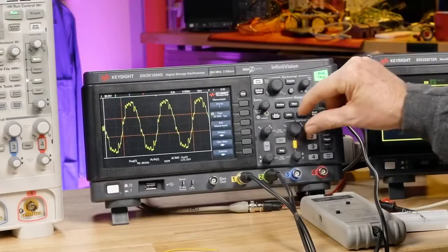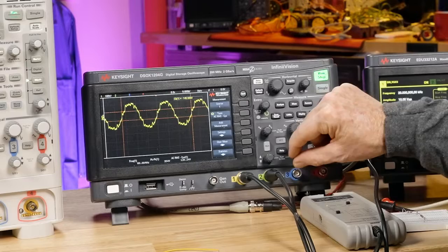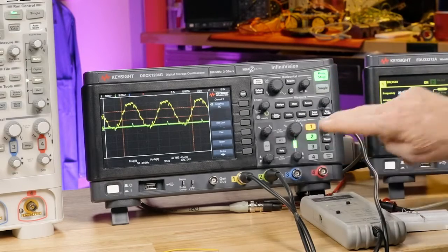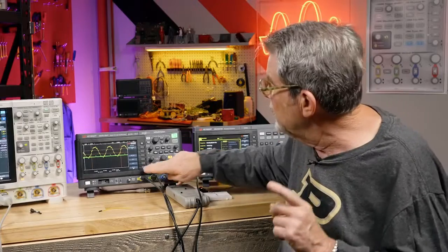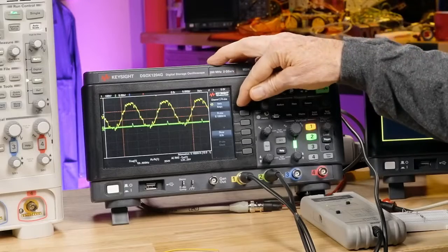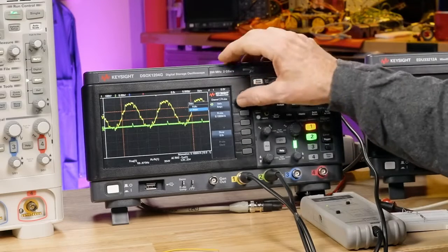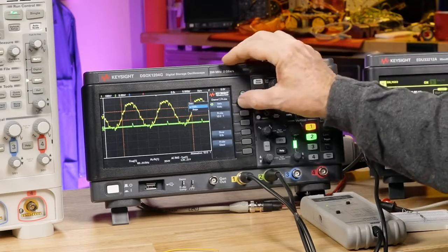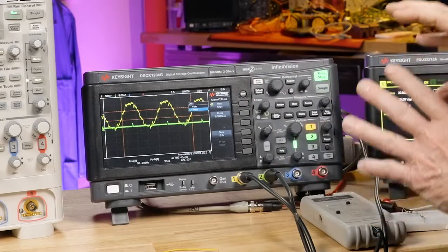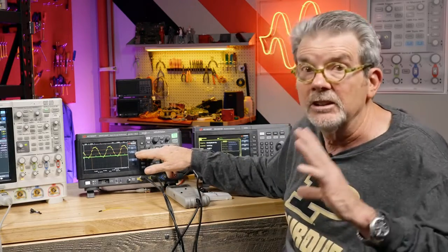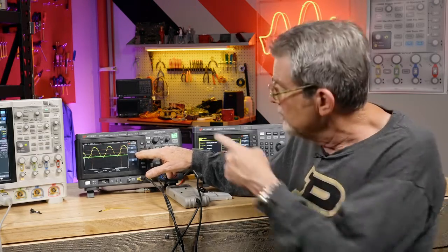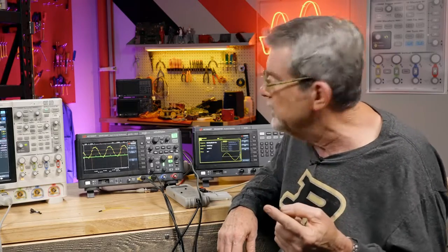Let's look at the current waveform. I'm going to rescale this first, move it up here, so we can separate the two. Turn on the current. Now I have to do the same thing. Go into the probe menu, and normally it comes up in volts. If I select amps, now it knows it's measuring current, so it's going to convert voltage to current. And instead of a probe attenuation factor, it has a conversion factor. In this case, I'm going to use the default 0.1 volts per amp. That's the conversion factor. That's pretty much equivalent to a 10 to 1 attenuation.